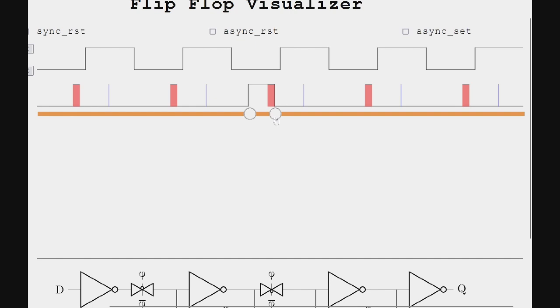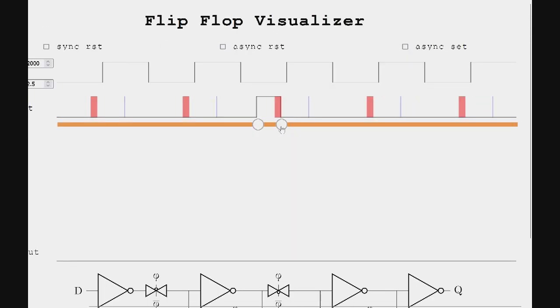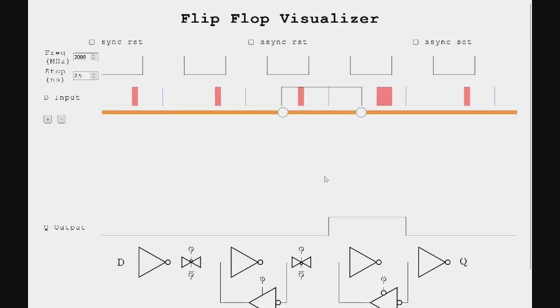So what is this violation called? This is a hold time violation, because I'm just a little bit too close to the end of this. I need to extend this outside of this timing aperture, and then it'll work. It goes for both falling edges and rising edges of our flip-flop. Okay, this makes sense. Good. That was a big information dump. This will be very helpful on your homework 3, because homework 3 is getting more in the weeds of flip-flops and their timings. So good.